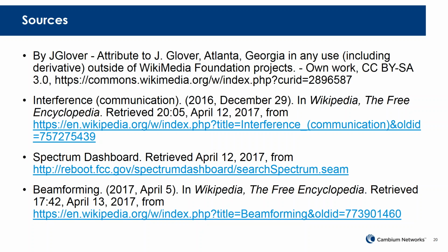So I think someone is just commenting that there are some horns that have 90 degree sectors and no null zone. Gotcha, RF Elements. Yeah, I'm getting a little bit outside of my expertise there. Last time I checked, I thought that the horn antennas had a little bit lower gain. They have excellent side interference rejection. They reject interference from any side sectors, I've noticed. But when I was speccing them, I think they had lower overall gain compared to a typical sector. But maybe I'm out of date on those.